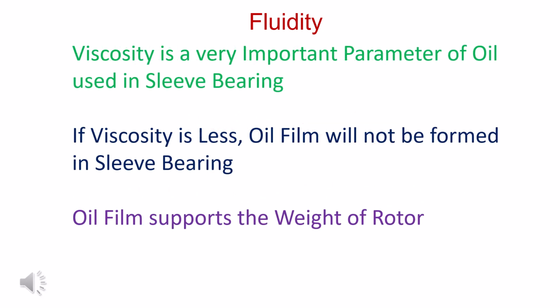Viscosity is a very important parameter of oil used in sleeve bearing. If viscosity is less, oil film will not be formed in sleeve bearing. Oil film supports the weight of rotor.